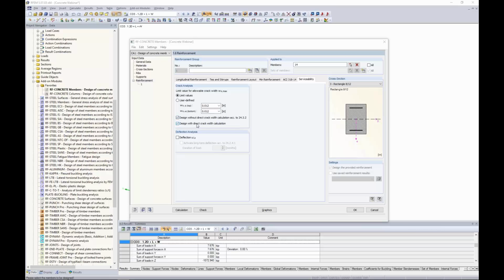Now, if you're looking for more of a comparison to an actual crack width, then we need to turn to some equations that are more theoretical. Again, they're not found in the code. So in our program, we refer to the Gergely-Lutz equation. This will calculate an actual width of your crack based on all of your loading and your criteria and such. So that's what this is about with our checkbox here.